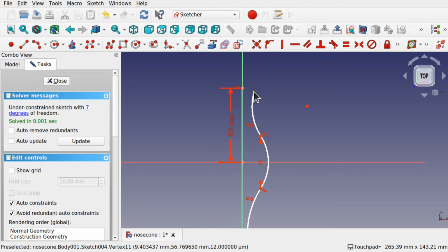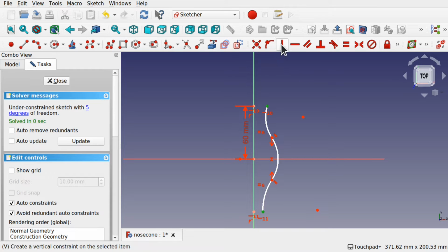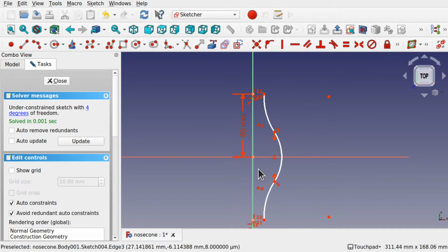And we'll take this point and make sure they're in line, so we get the right dimensions, and also the same for this one. Make sure those are in line. So we can move these out, but I'm going to take also these 2 points and make sure those are in line with a vertical constraint. So we've got our shape, and we've got 3 arcs, 1, 2 and 3. This is important because we're going to match this number when we do our front profile.